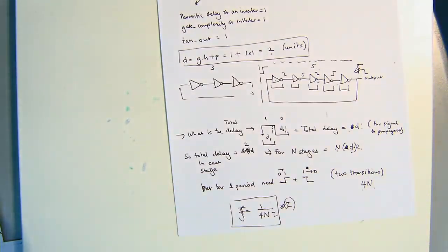I also gave you a little bit of background, not relevant to the exam, not relevant to this course, but when you're employed and actually building chips, one of the tricks people usually do is put ring oscillators on the chip, all over the place, so you can tell what skew you've got on your actual process. Are you on a fast corner, or on a nominal corner?